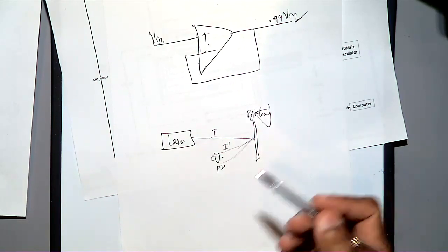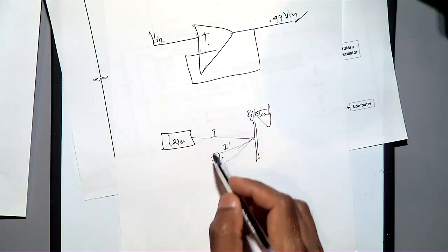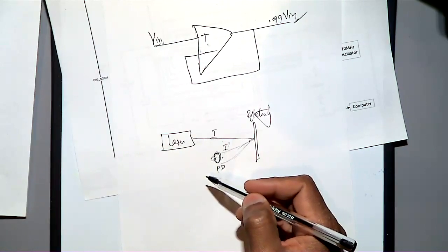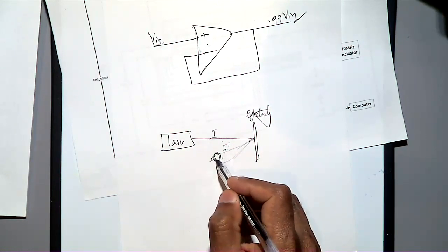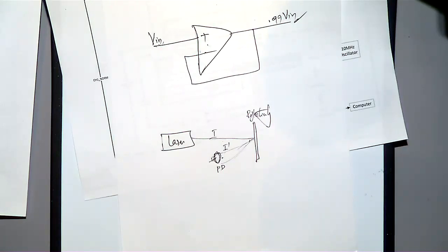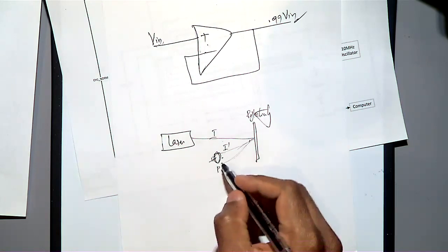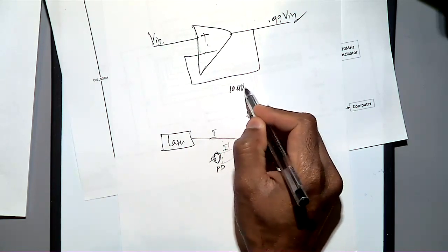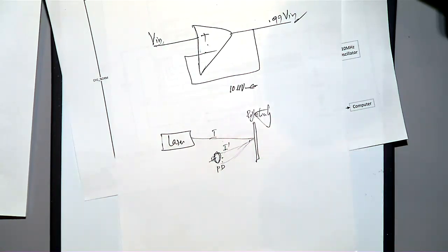So different reflectivity. So this much is clear. Then after the photodetector, your ESD knowledge, DSO knowledge will kick in. We will clearly tell you the photodetector output is voltage. Usually a photodetector gives current, and then you need a current to voltage conversion, but we will tell you the photodetector gives voltage, and it is low. We will say the photodetector output is in the 10 microvolt range.